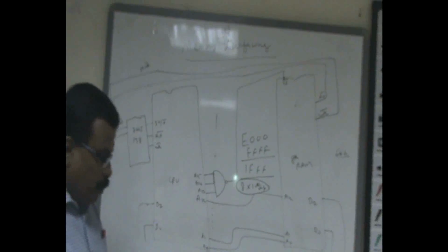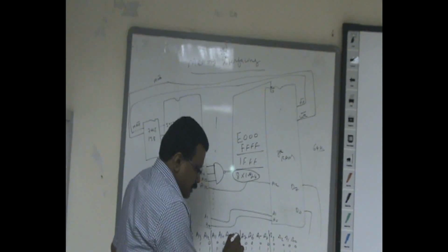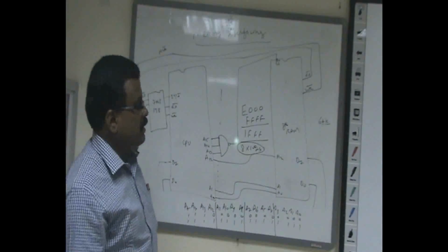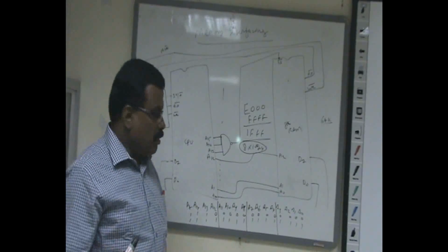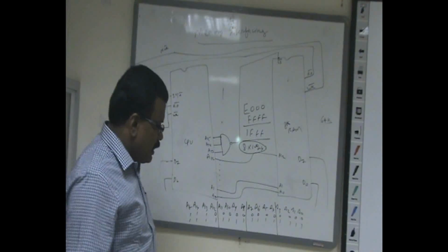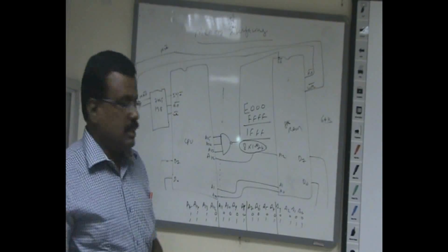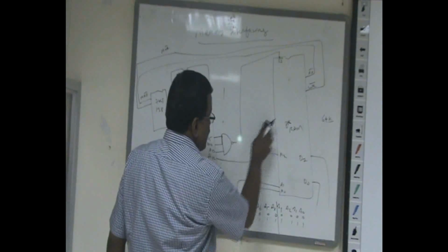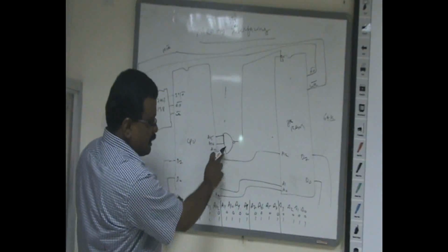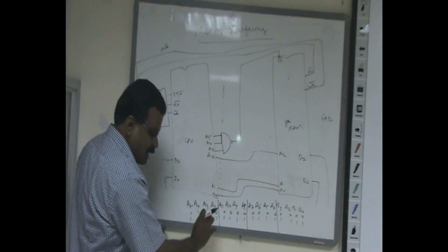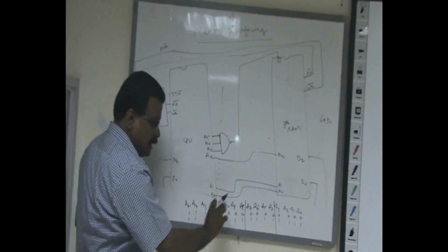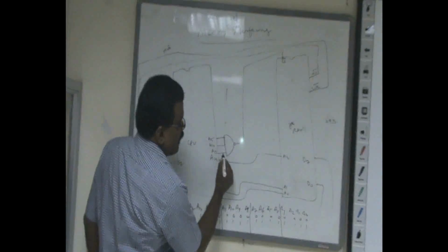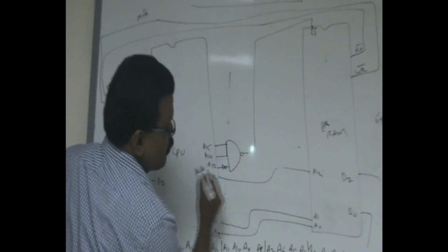Now, whenever you do programming in the lab, on a microprocessor kit, there are different companies like VI Microsystem, Frontline, and ALS. They are the popular kit manufacturers. You can see every kit has its own starting address. Somebody may have a starting address of 8000, someone may have 4000. That is because of these reasons. Suppose the decoding logic is like this, your address space for this memory is E000 to FFFF. That is our working space. Instead of this, suppose I use one inverter here, I can use one inverter here.